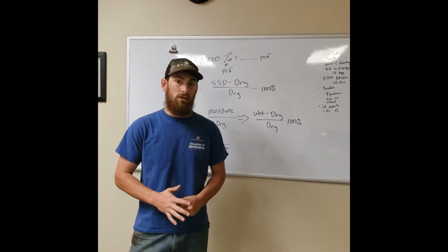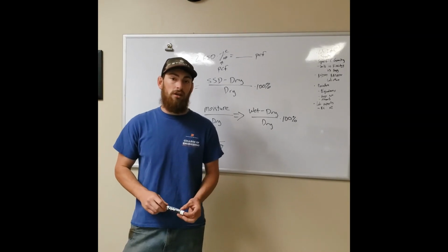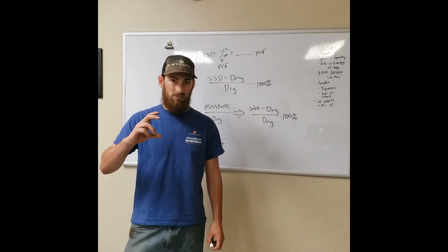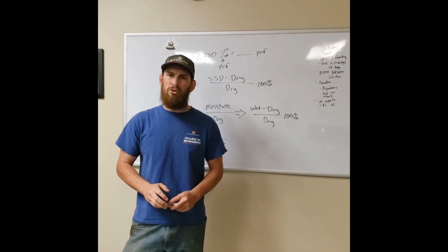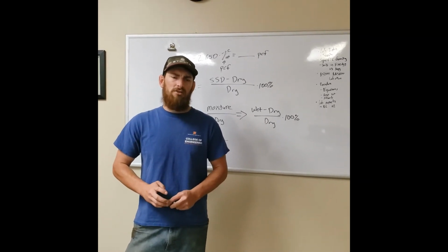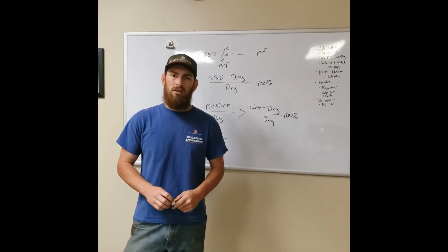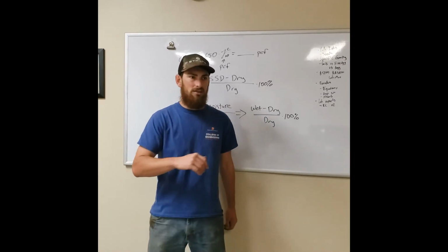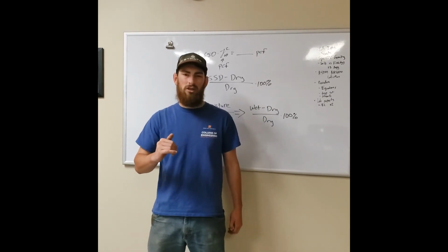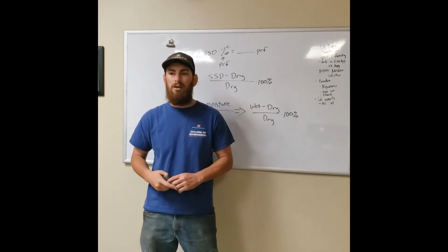Your executive summary goes right at the top of the report after you have your title page, or the way that you address that lab report. The executive summary, all I want is your final results. I don't need the data. I just want the specific gravity is this, the absorption content is this, the moisture content at SSD is this. That's all it is, nice and short.